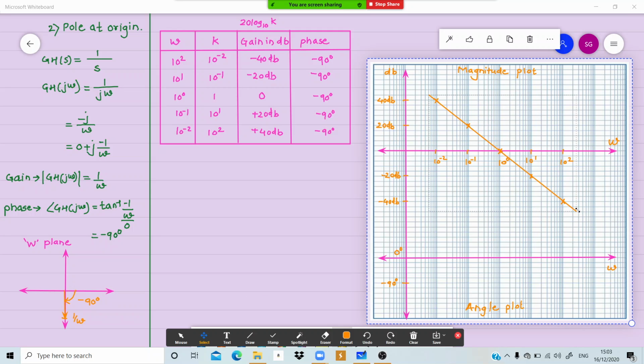Still it is now 20 dB. Now just see what is the slope. Slope is, it is decreasing slope, right? So minus 20 dB ka slope it is there, and per decade. Now what is the meaning of decade? Multiplication by 10. This is getting multiplied by 10, you are going over here. This is getting multiplied by 10, you are going over here. So this one span is a decade, and for every decade it is getting decreased by minus 20.